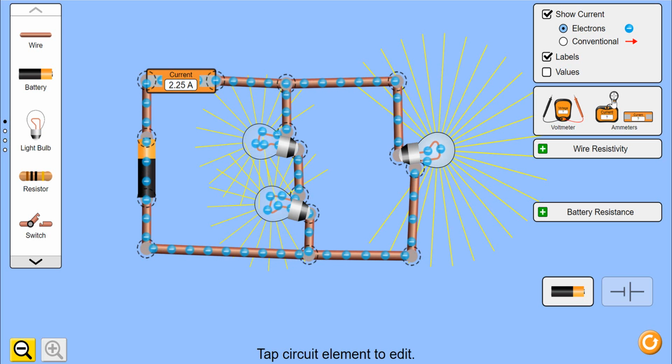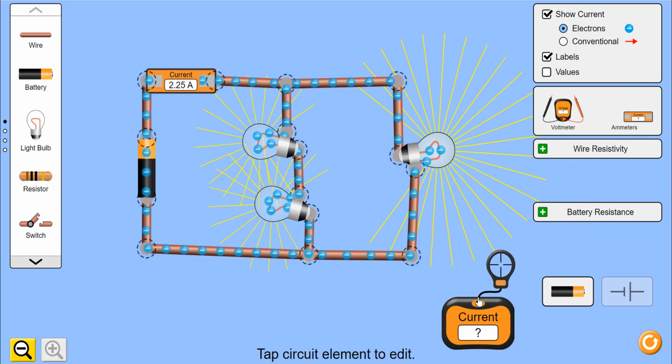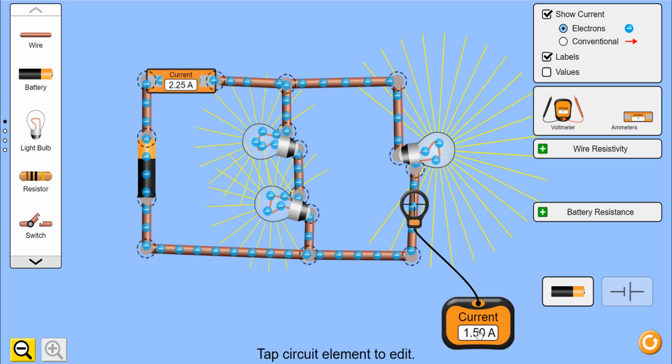So what I'm going to do here, just for convenience, I'm going to stick my ammeter. Just for completeness' sake here, I'm just going to put down the current meter. I could have actually built in an ammeter. I guess this is a little clever. Just be careful, ammeters do have to be measured in series. So like this one here I showed, it actually does have to be in the pathway.